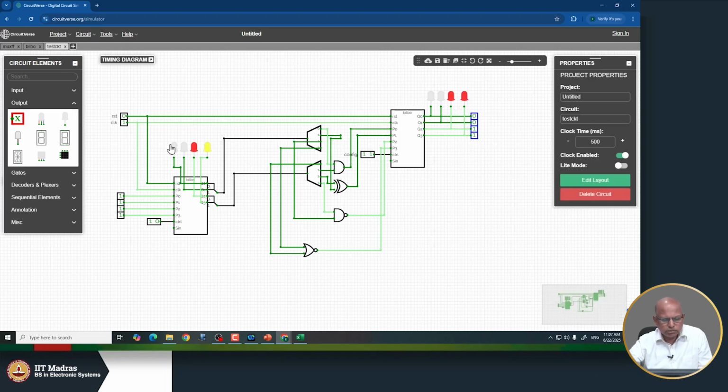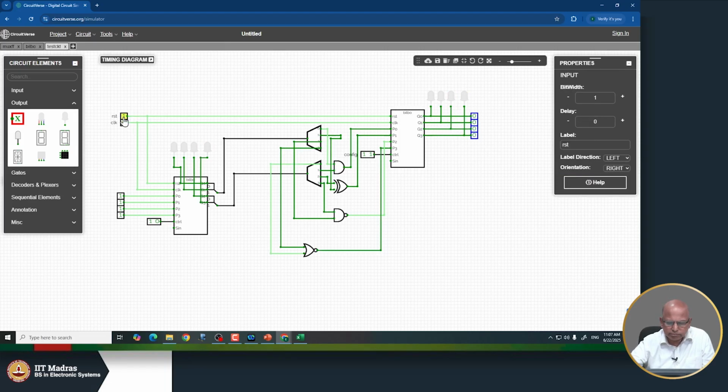Okay. So start with reset. Okay, everything is off. Then go back to reset 0, clock 0. Then maybe start with this state 1111. So clock it. So it went to the 1111 state. So now when I keep clocking, this will go to all kinds of states.